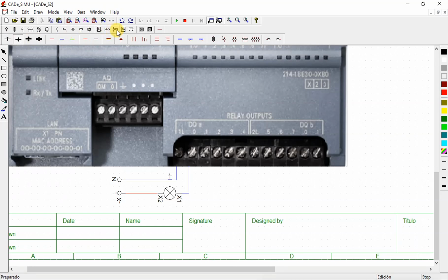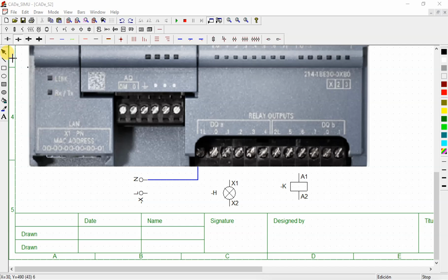Then we are going to have a coil which is going to act as our contactor. Yeah, allow me just arrange the things like this. So now we are going to have this live. It is the same live which is going to come here to the contactor.